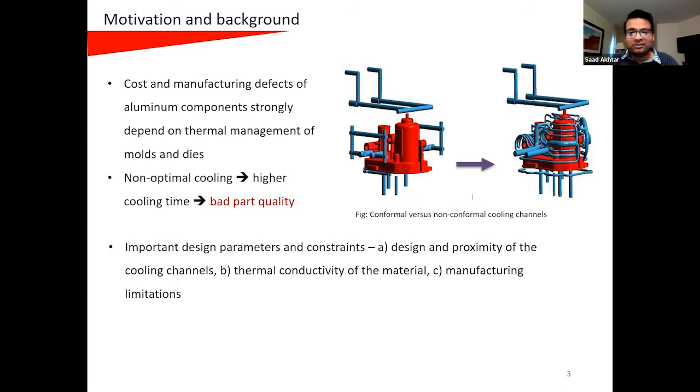With straight channels, the good thing is that the manufacturing technologies are pretty robust, and you don't need complicated part manufacturing technologies. But with conformal cooling channels, you need to make sure that whatever you're designing, you can manufacture. That was a big part of this project.